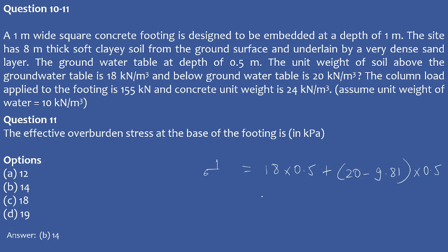So 9 plus, if we assume this is 10, they must have assumed the unit weight of water is 10, so it's nearly equal to 14 kPa. So that was just an effective stress calculation at the base.